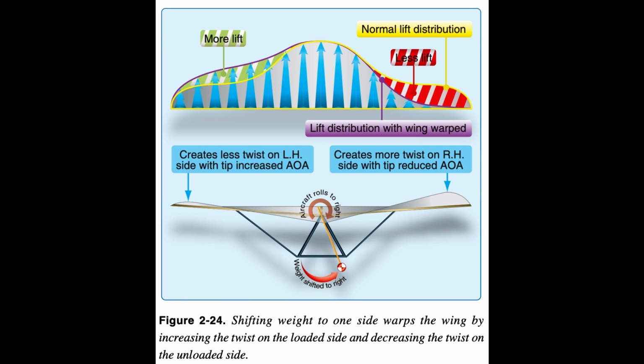Typical airplane wings generally pitch nose down or roll forward and follow the curvature of the upper airfoil camber, creating a negative pitching moment. One of the reasons airplanes have tails is to create a downward force at the rear of the aircraft to maintain stabilized flight, as explained in greater detail in the Pilot's Handbook of Aeronautical Knowledge.